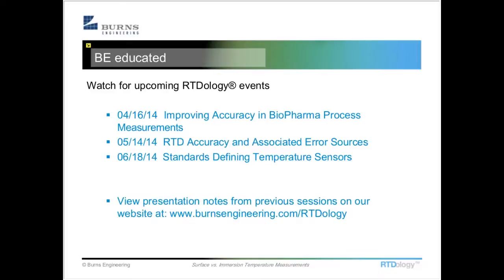So it really depends on how accurate you want that measurement to be. And in a 4-wire system connected to a device that has a capability of doing a 4-wire lead compensation, you don't have to worry about the individual leads varying in resistance, because it compensates for all of it no matter what it is.